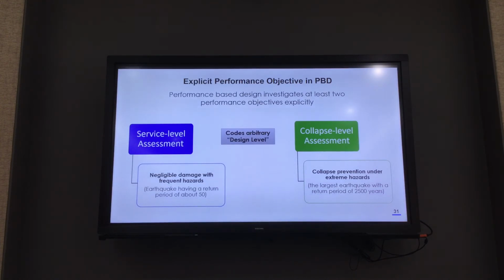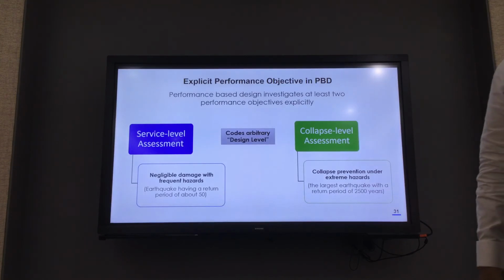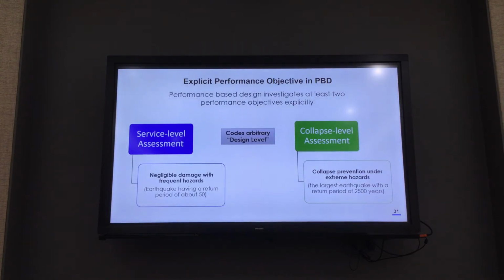So 300 kilograms per square meter, and this room is 6 meters by 10 meters, 60 square meters, multiplied by 300. How much is that? 18 tons. Okay, 18,000 kilograms.